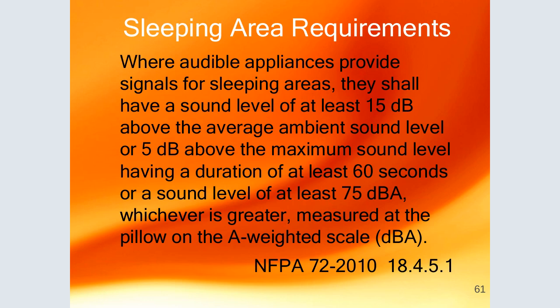Sleeping area requirements. Now, where audible appliances provide a signal for sleeping areas, they shall have a sound level of at least 15 decibel above the average ambient sound level, or 5 decibel above the maximum sound level, having a duration of at least 60 seconds, or a sound level of at least 75 decibel, whichever is greater, measured at the pillow on a weighted scale.